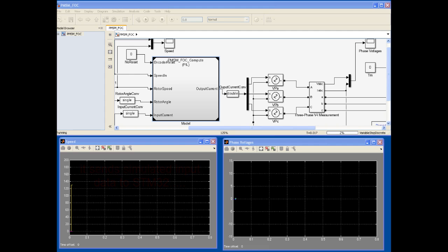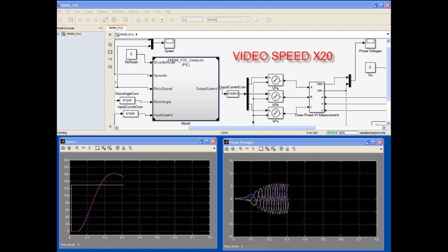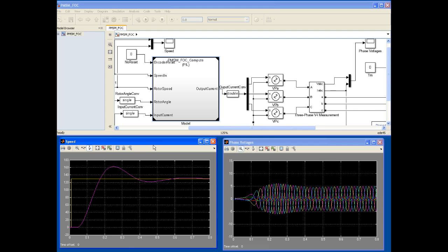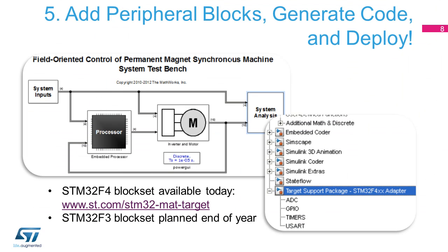Then Simulink uses a serial communication link to send input data to the STM32 target. The STM32 target computes data and sends back results to Simulink for the user to compare with the pure simulation results we previously got. We are fine with the regression algorithm executed by STM32. Let's switch now to the final step in the code generation process.